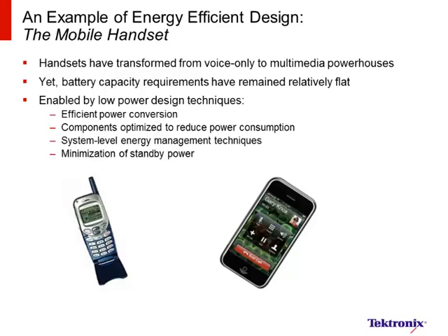First, we'll look at power conversion. The different circuits inside the handset often require different supply voltages, necessitating that each circuit has a separate DC to DC converter. Traditional converters used linear regulators, resulting in efficiencies of 50% or less. Clearly, there's a huge opportunity to improve efficiency. To address this, today's designs use switched mode techniques, which can provide efficiencies of 90% or more.